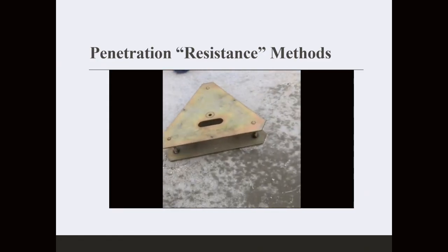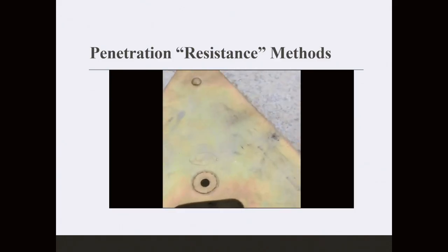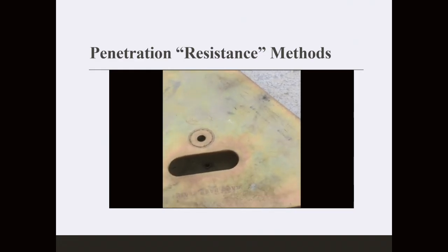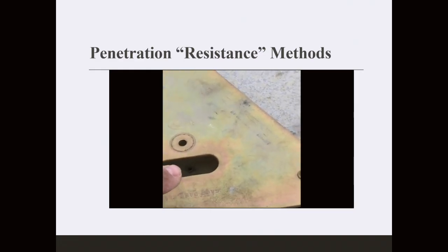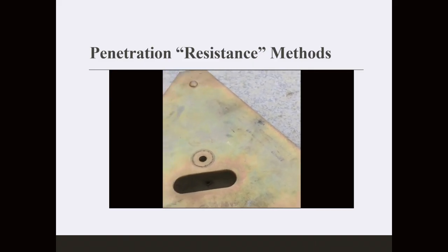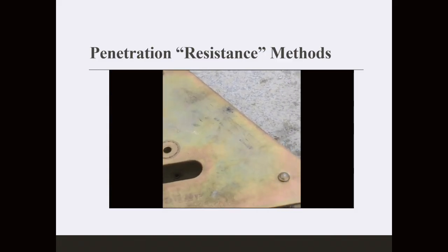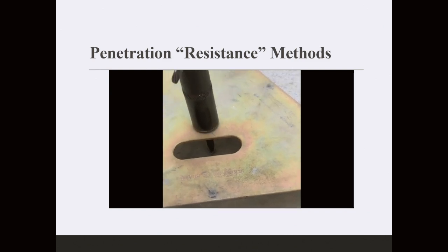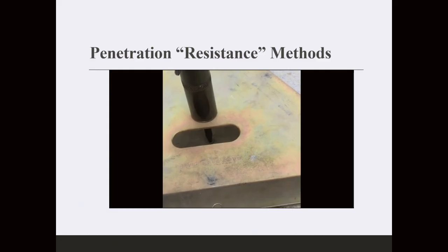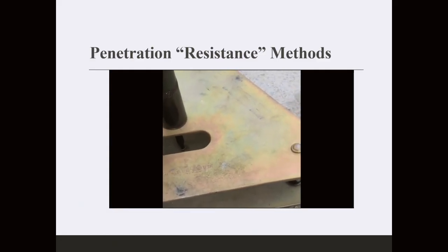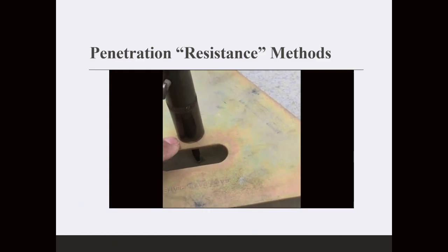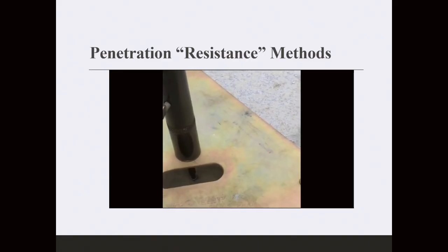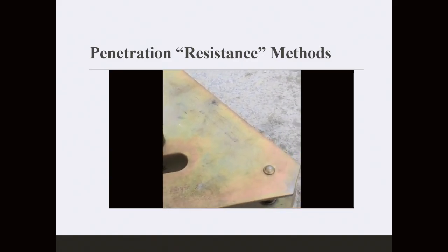So this is what this looks like. I don't know if you can tell, but down in that hole, there's a little dent. So what you're doing is you get your tool. I have the set screw set, so you set it through the top hole, and you put the tip in the bottom dent. If you notice, the shaft is all the way on the top plate, and this goes up and down, but what I did is push it all the way down, and then you set your set screw.